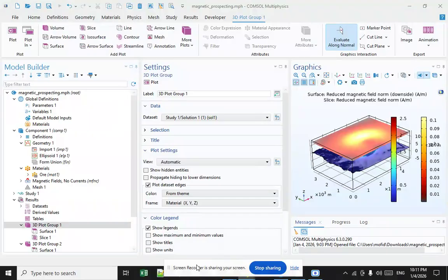Direct reduction requires more energy as the temperature is higher and the time is longer, and it requires more reducing agent than magnetizing roasting.